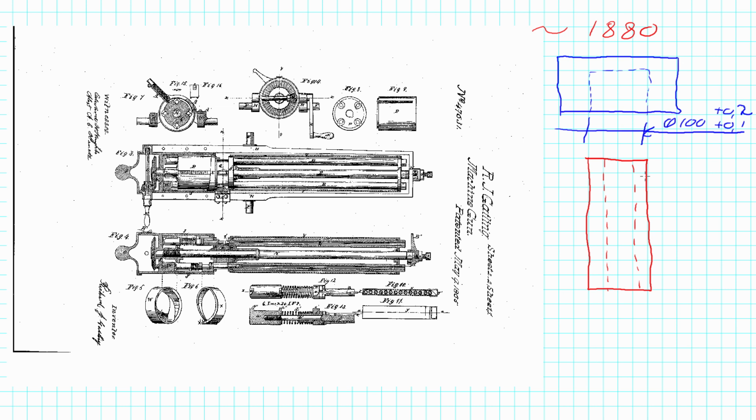So it's a little over 100, and we may put a tolerance on the barrel and say that, again, it's a diameter, and so it's 100, and maybe the top tolerance here is plus 0, and the lower is minus 0.1. By keeping those dimensional tolerances, we ensure that we can fit this barrel into this end piece.